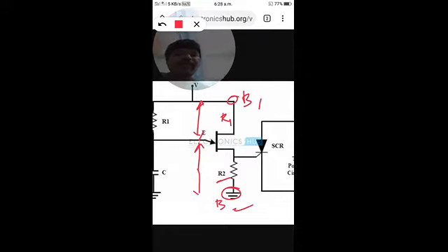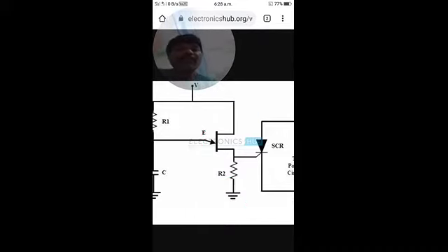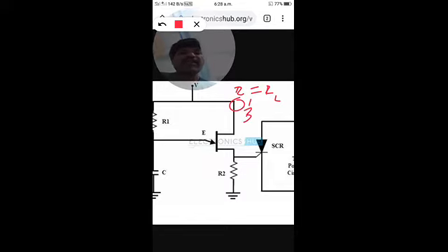Here the resistance R1 is almost equal to R2. That is because the intrinsic semiconductor material is distributed equally from emitter to base 1 and from emitter to base 2. Therefore the resistance RB1 in the base 1 region is almost equal to that of the base 2 region. So R1 is equal to R2.